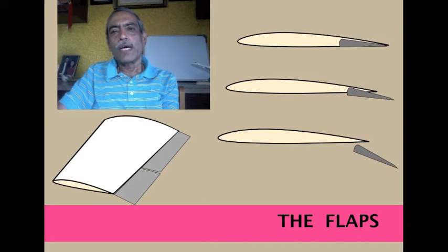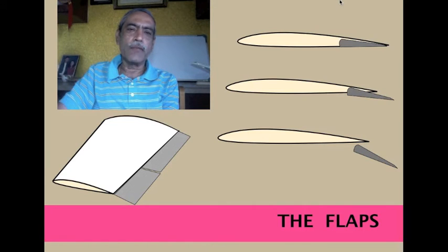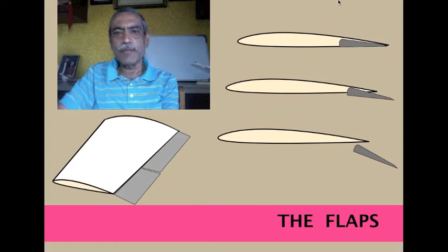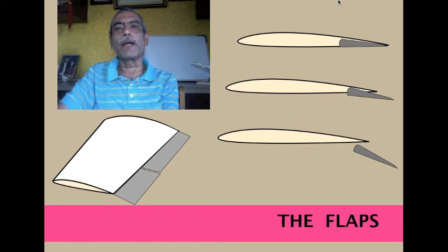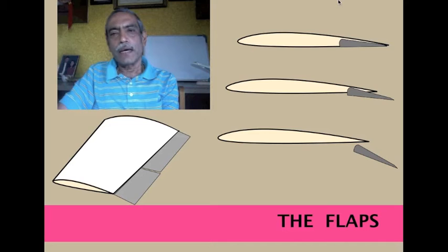Even though the rearward force, the drag force, which we talked about earlier, is going to increase with the lowering of flaps because of the frontal area which it's projecting, the advantage of its lifting capability in this phase of flight for the takeoff and landing outweighs the increased drag.